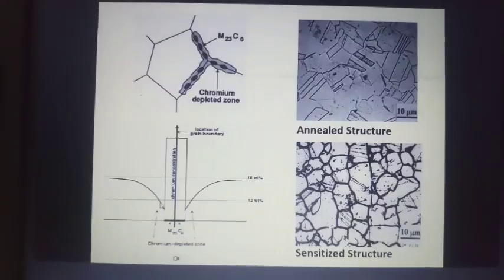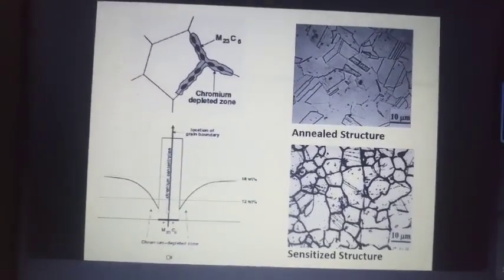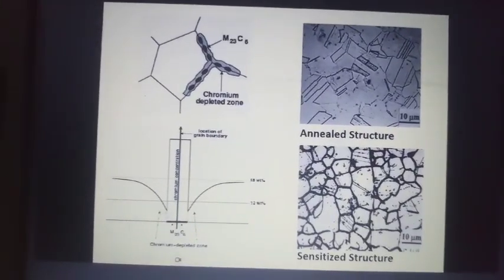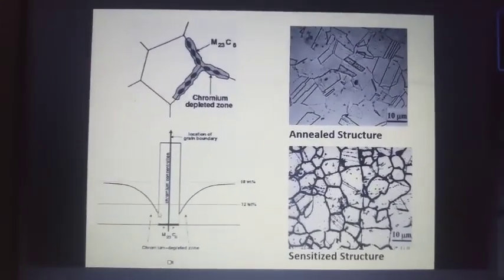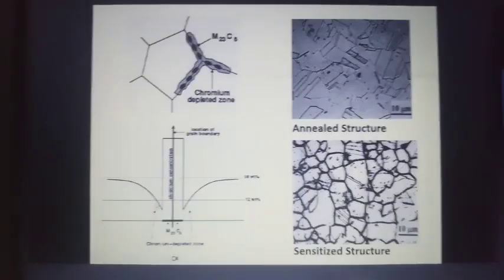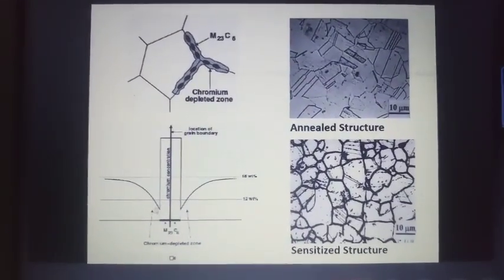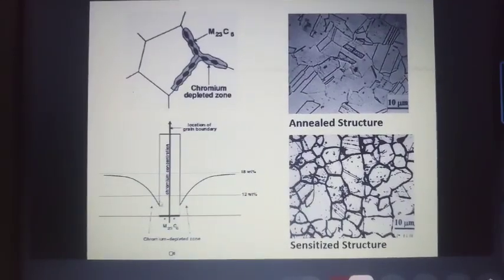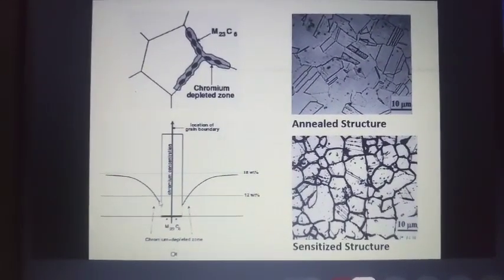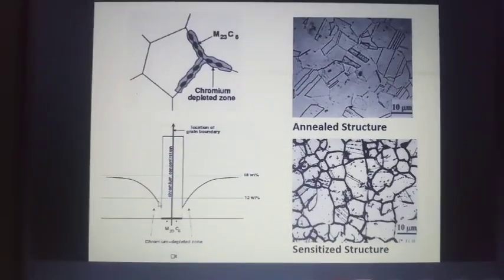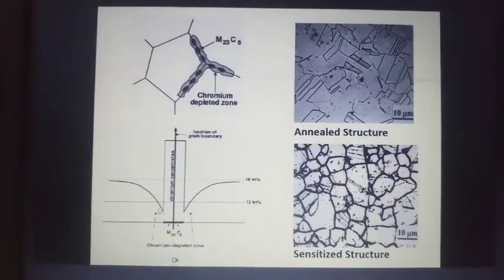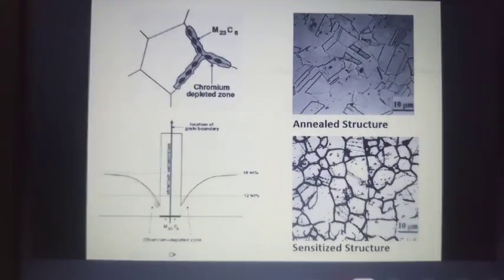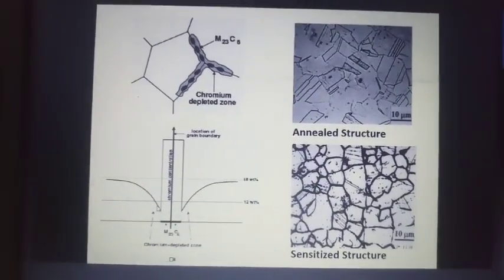12% I told you the first one. Yeah, but if you see near the grain boundary, what is the chromium you have seen? Less than 12%. This is like 5.8%, 6.8% like that here. This is like a typical low alloy steel or typical low carbon steel, low carbon without chromium or low alloy steel with very limited chromium. So if you have this region in a stainless steel, then you are undergoing corrosion, right? It will have intergranular corrosion.